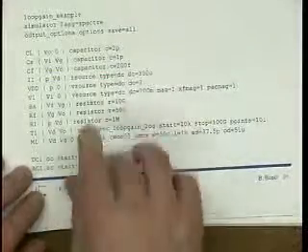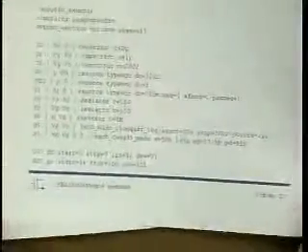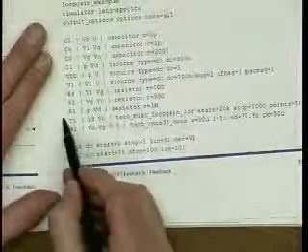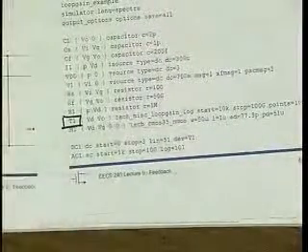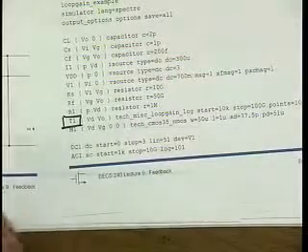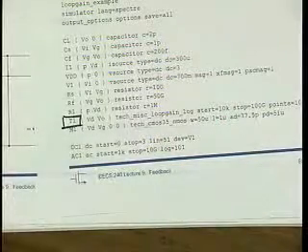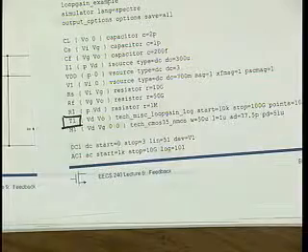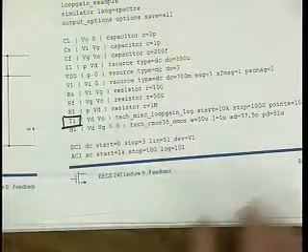Then I type in the netlist for my circuit, and Spectre has a slightly different syntax than SPICE, but you can probably easily decipher what that means. And here I also refer to another sub-circuit that I call T1, and in that sub-circuit I have put in all of that funny stuff where I test with one source and then I test with the other source, and I collect several results. And I use this alter statement.